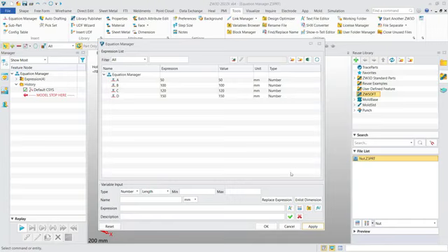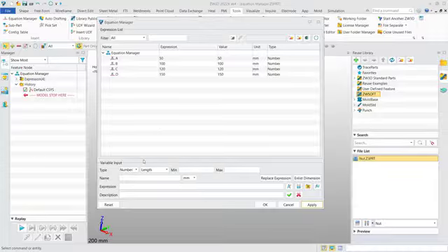Okay. And on the lower area is the creation panel, which is also one of the most important parts. Here we can input many variables. First, we can see the types. We have 4 types in ZW3D: number, string, point, and also vector. Okay, so basically we use the number at most.